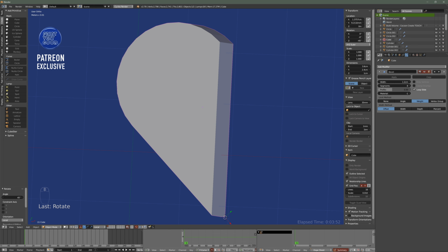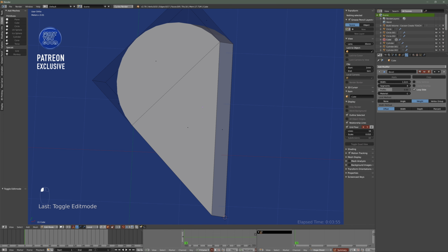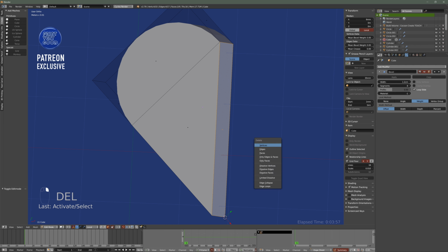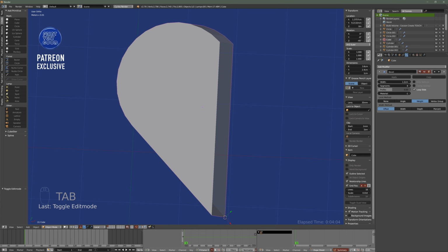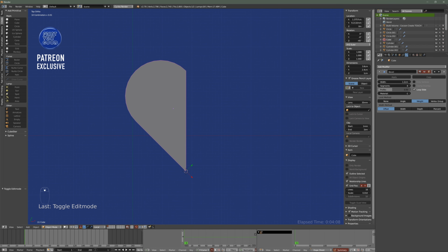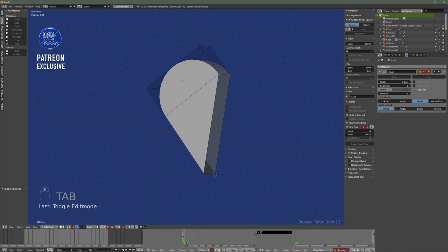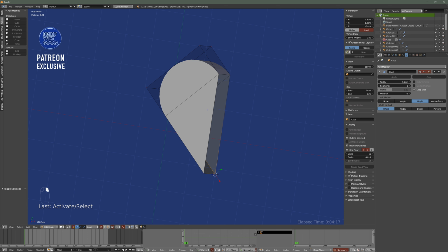this face here, because I'm going to mirror this and I don't want any internal geometry inside this geometry, because that'll create a non-manifold mesh. And let's just hit Alt-G. Actually, before I do that, I'll select this vertex down here, switch to vertex mode, and I'll just make sure that my cursor is snapped to that vertex.